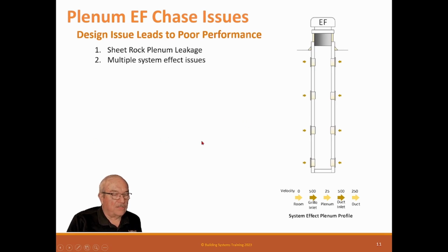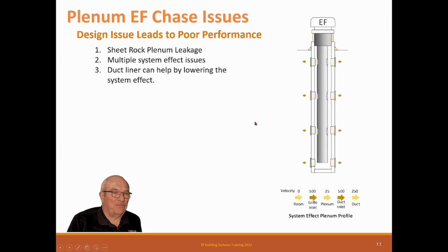because it has to be such high pressure to make up for all those losses. And I've seen guys that have tried to clip down the ceiling to keep it from coming up. The problem is it needs a duct to go to the space one time. It should not be going from plenum space to plenum space to plenum space. And designers need to know that. It'd really be handy if designers could work on a test and balance crew for just a couple of weeks to realize that this stuff's all important for balance.